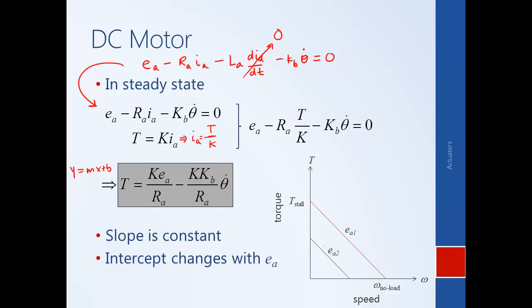Such a thing, a torque speed curve like this, can be used for sizing a motor. It can even be used for control in some instances, but you lose some elements of the motor's behavior, its transient response. But in some instances, this may be sufficient. In practice, the maximum torque of a motor is usually limited.